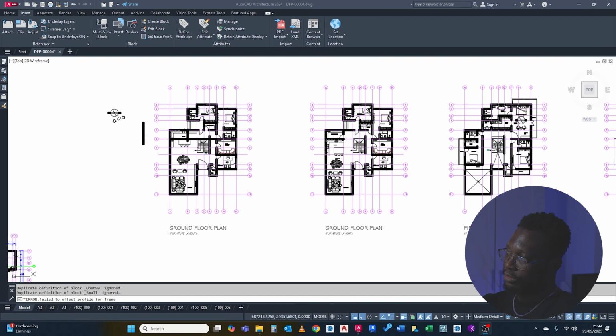Today I'll continue on this floor plan. I'm going to pretty much work on the section. So what I tend to do is I do the floor plans first, and then I move on to the section, and then the section helps me to develop a 3D or an elevation because it gives me the levels, the heights that I want it to be. And I tend to start my sections with the staircase because that gives you the right levels. So yeah, let's get into that.